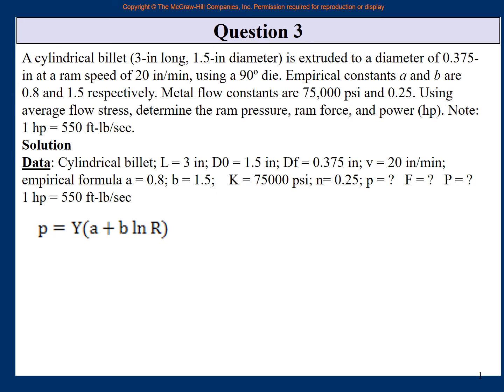Why would you go to ideal and this and that? See, in the previous problem on wire drawing, they used an indirect method: they did not give the equation for redundant work, but said redundant plus friction is equal to 40% of ideal. This time they are saying just use the experimental equation. So don't go into an unknown area. Sometimes I give you 2-3 marks just for attempting it, but I become really upset and give a big 0 if we say empirical constants are given and you use the ideal force. So please read questions carefully, give it one extra minute, but always read it carefully.